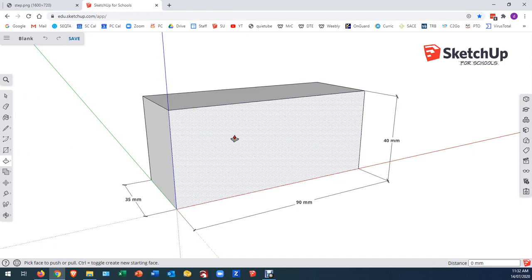You'll notice that that little surface there was a rectangle, so all I really need to do is come here and take the rectangle tool, start in this corner and drag a new rectangle, and we know that the length of the rectangle has to be 40 and the height has to be 20. Now I've managed to get that exactly right if you have a look in the dimensions bar, and I could click at that point, but it is still better to type in 40, 20 because I know it is precise that way. There I have my rectangle.